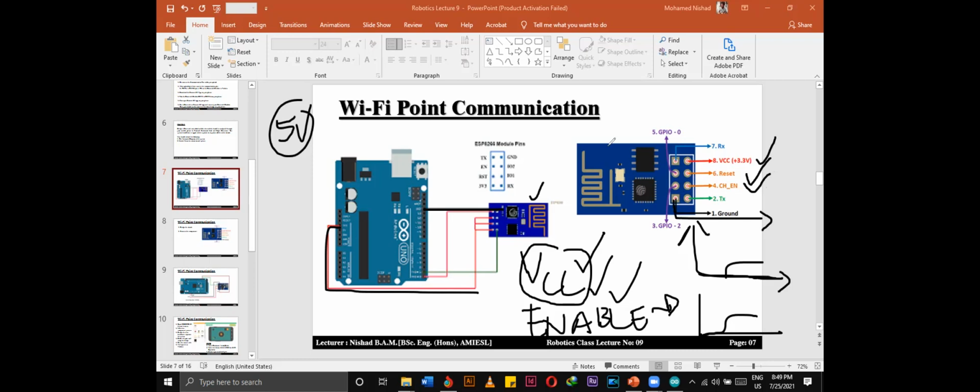If you obtain this Wi-Fi module, it explains the wiring terminals itself, right? So you don't have to worry about these things. That's all. In the Bluetooth module, we have 4, right? In the Wi-Fi module, we have 6. That means 3 VCCs, 1 ground, and TX and RX pins.